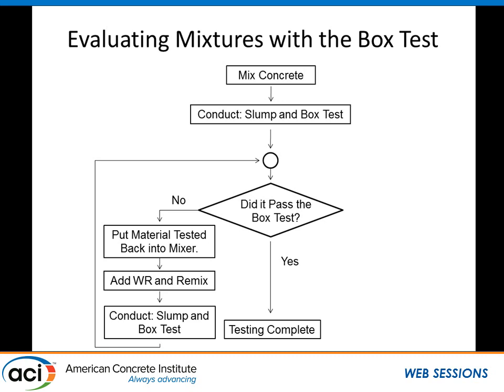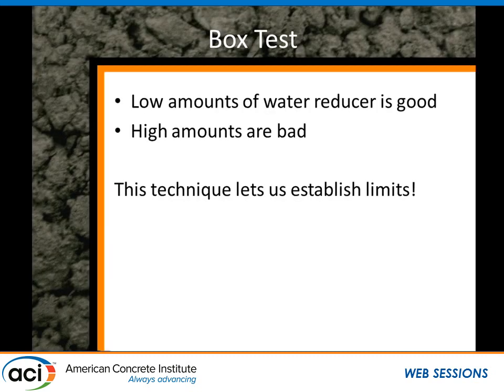It's not one we want. A mixture that requires very little, that's the stuff we're after. Why do we use water reducer? Because if we used water, we would change water cement ratio, we would change paste volume. We would change the actual volume of our mixture. If we use water reducer, we haven't changed anything. Does that make sense to people? It allows us to rank mixtures, head to head, compare mixtures.